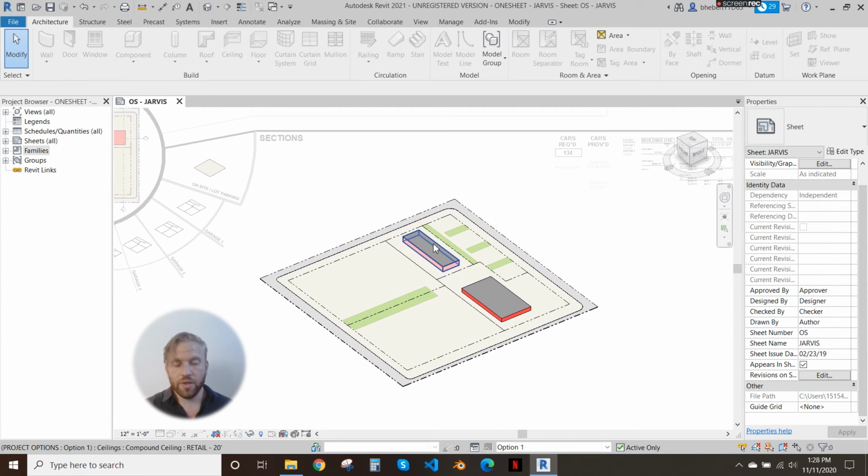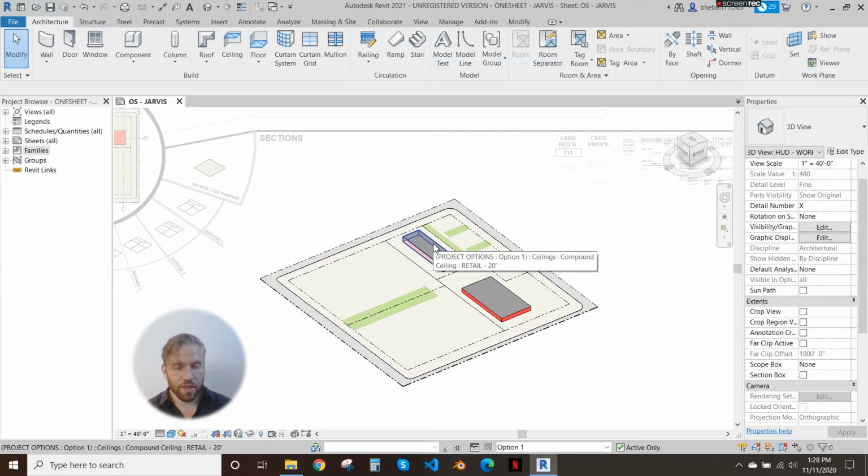So in here I have 10 levels placed. I have three below levels and 10 levels up, and they're all set at 10 feet. I don't ever want to change that. I want to offset from that, because working with levels is a pain, and when you have multiple buildings, you don't want to have multiple levels. It ends up being really time consuming to change all of that. So I'm ignoring that for now, and I'm just saying this project can do up to 10 levels. You can make more if you like, which we'll talk about in a future video.